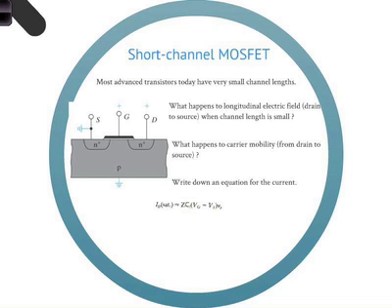Vt is what's required to create the inversion layer. So you have to subtract that, and this is the voltage that comes across the oxide, times its capacitance gives you the charge. Right? Treating the oxide